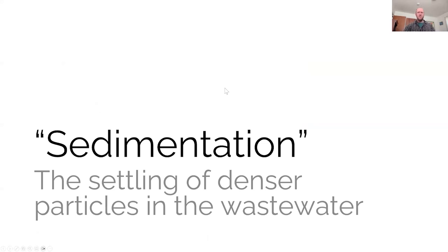Okay, and then the next term is sedimentation. So this really is just the settling of denser particles in the wastewater. And this is, of course, what the whole thing we're talking about here is. This is accomplished by slowing down the wastewater stream. So the slower water moves, it no longer has that energy to keep things suspended. And so once it slows down, things settle out.